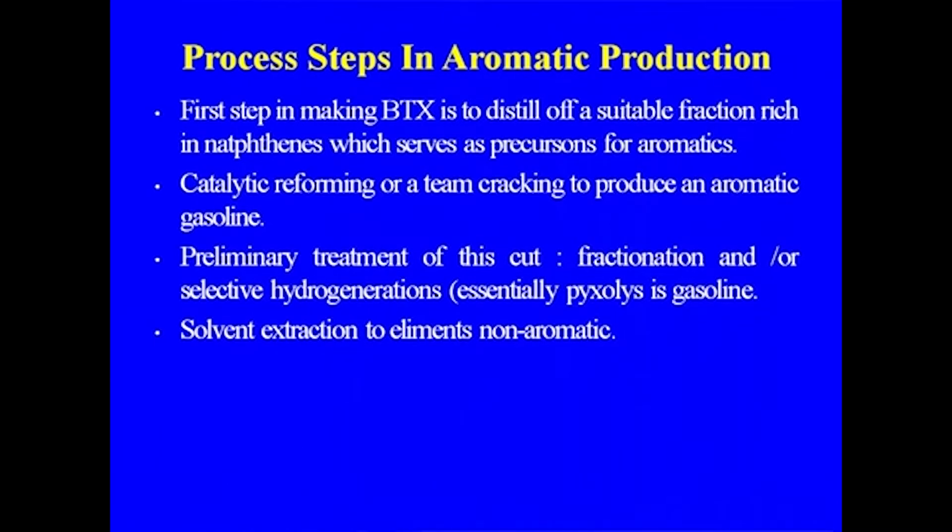Catalytic reforming or steam cracking produces aromatics, because the pyrolysis gasoline can be combined, after hydrogenation and removal of impurities, with the reformate for separation of the aromatics.